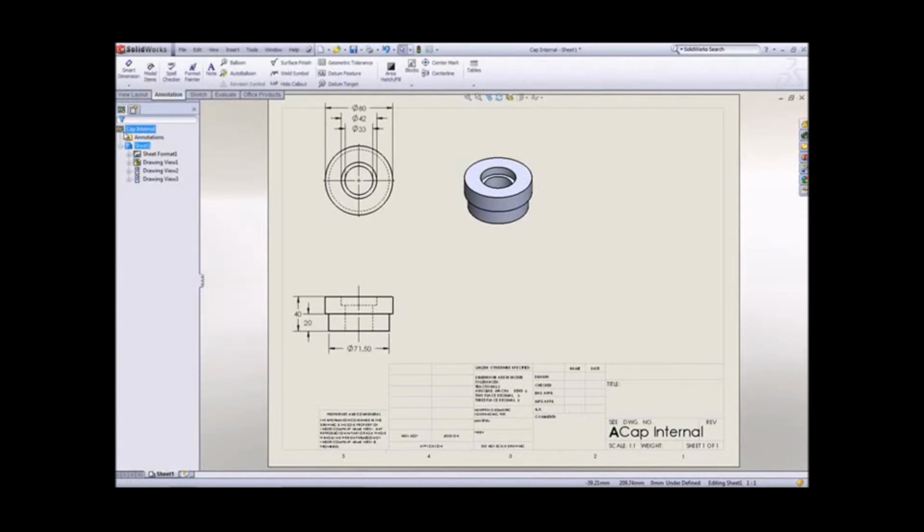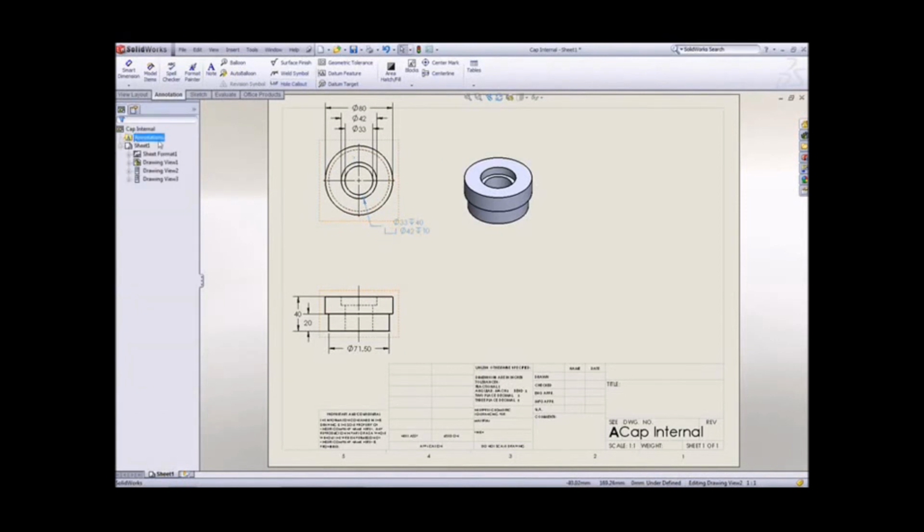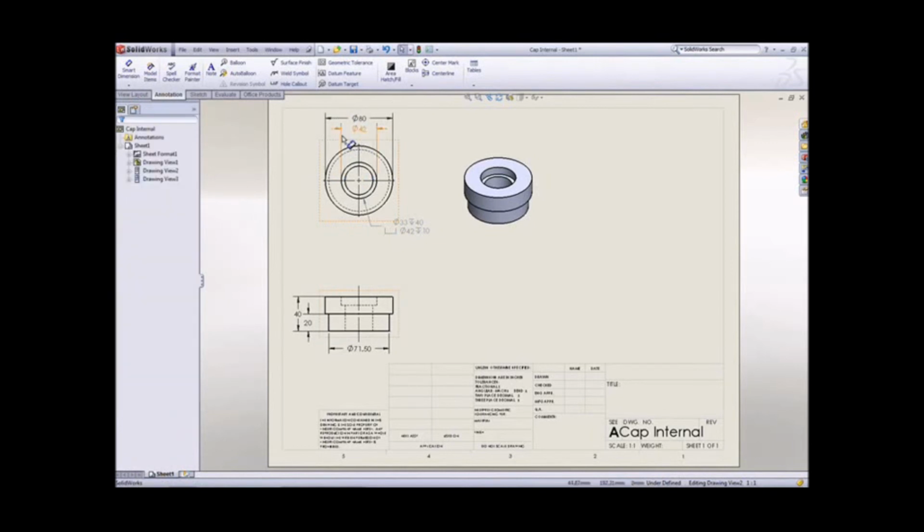To comply with drawing standards and reduce clutter, you need to rearrange the dimension labels on the top view. Click Whole Callout under the Annotation tab. Select the middle circle and place the callout. This annotation labels two diameters in a concise manner. Click the green check mark. Now you can delete the repeated dimensions by selecting them and pressing Delete.